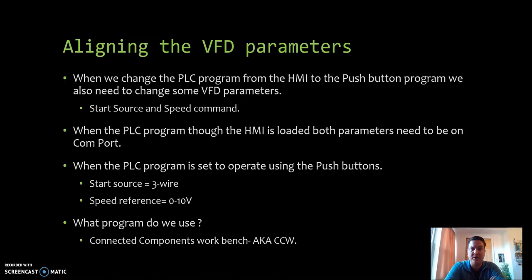All right, one thing that I really like to touch on that got cut short in lab is changing the VFD parameters. The reason why we're doing this is because the VFD is set up to look through its COM port when we're working through the HMI screen for the start source and speed reference. So when we have that PLC program in there, it's anticipating getting information through Ethernet communication. When we put in the PLC program that works with the push buttons, we have to go into the program, which is CCW, and upload the entire drive. We should be online and connected to the drive when we make these changes. And we want to change our start source to 3-wire and our speed reference to 0 to 10 volts.